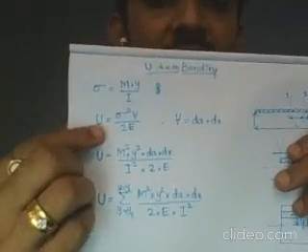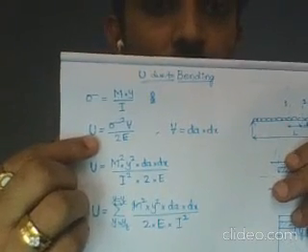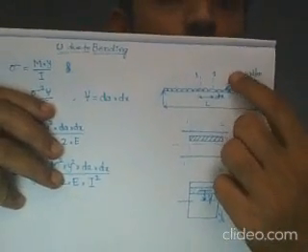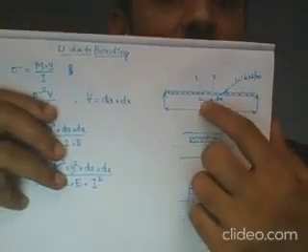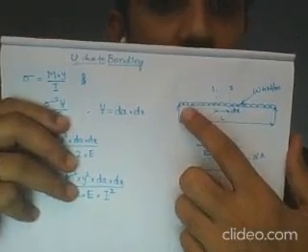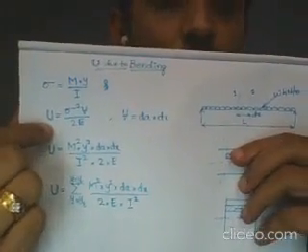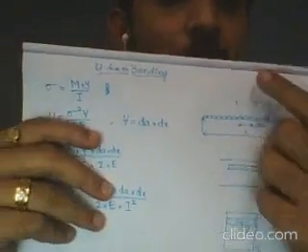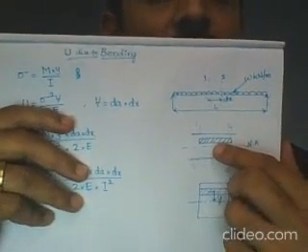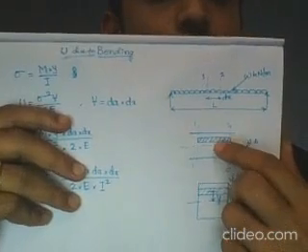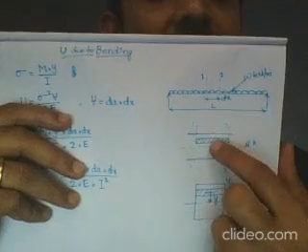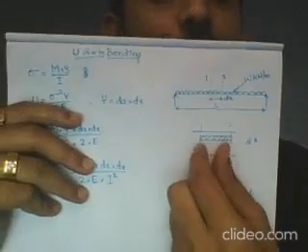Now when we say strain energy, there has to be deformation, not deflection. When we use a simply supported beam and apply a load from the top, there is going to be deflection at the bottom in the downward direction, whereas that is not deformation. For strain energy we need a deformation. So how exactly are we going to understand this? When the load is applied from the top of this beam, if the element is above the neutral axis, there will be compression acting. If the element is considered below the neutral axis, it is going to be tension.